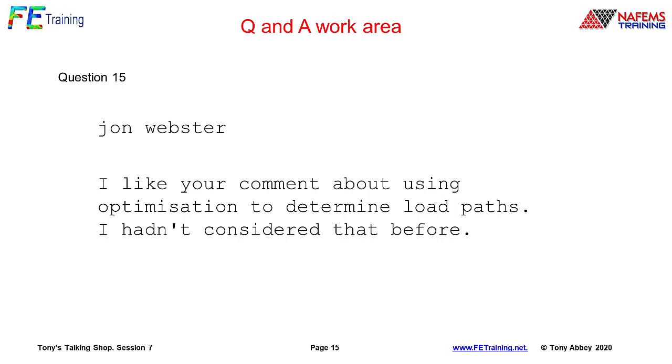John says he liked your comment about using optimization to determine load paths. I hadn't considered that before. I really believe in trying to understand stresses, and as I mentioned previously, looking at free body diagrams is extraordinarily difficult. Optimization can help you actually determine and perhaps emphasize these load paths and understand what the structure is trying to do. You've got load going in, load coming out, and what the optimizer is trying to do is the most efficient distribution of material to achieve that, subject to the objectives we've talked about. So it can be very, very useful to understand what structures are trying to do.